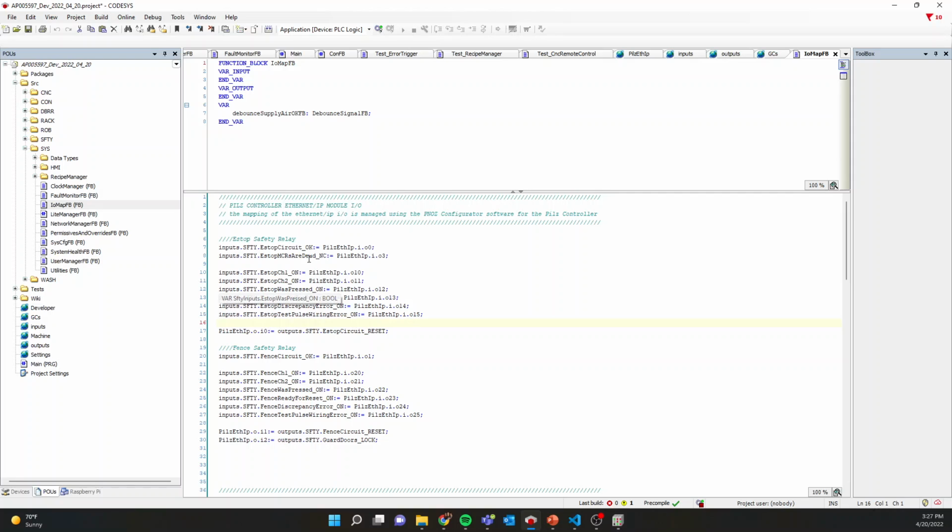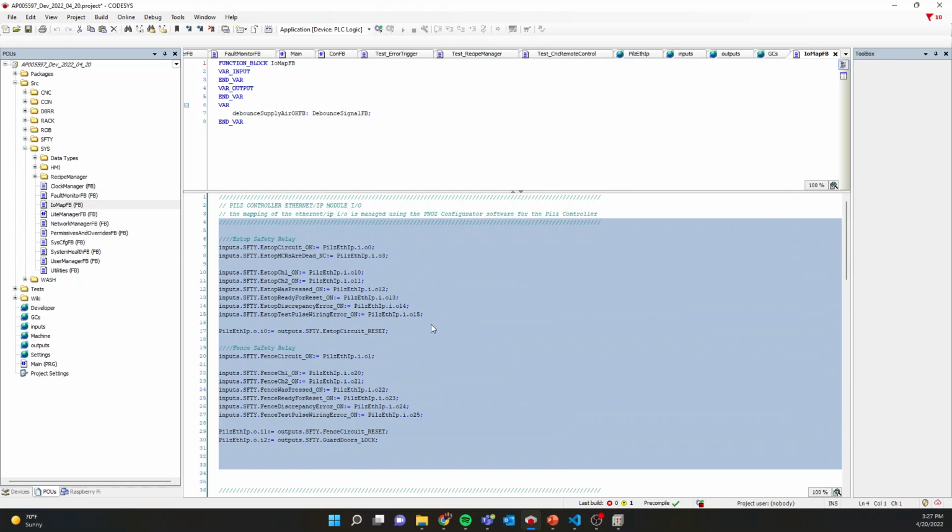This is extremely helpful in organizing the inputs and outputs, because one of these IO cards may go out and you may want to quickly remap it, you'll figure out a new solution and remap it to the variable that you're using throughout your code. I'm not using this variable in the code anywhere other than right here. This is being used in the code, so this is a pretty typical strategy. Typically we want to separate the hardware layer from the software layer, and this is where that happens a little bit right in here.